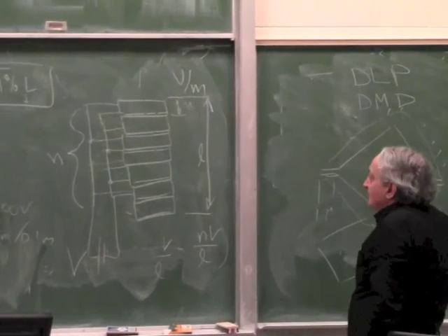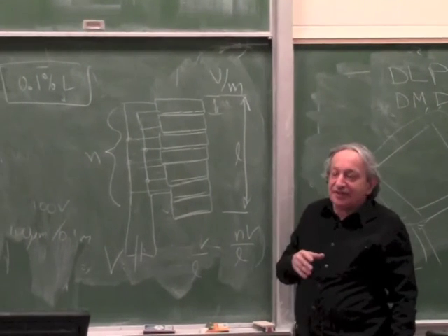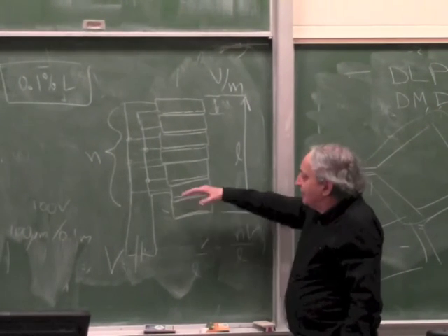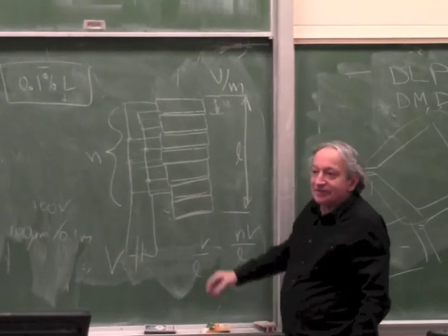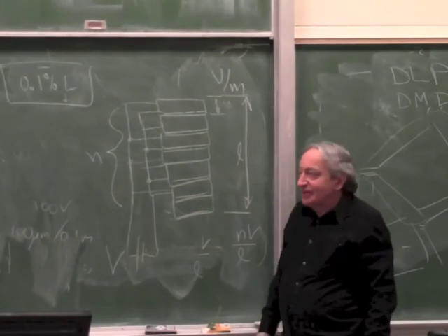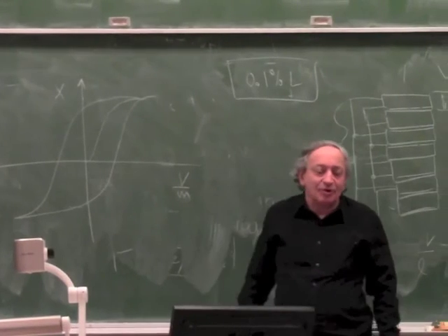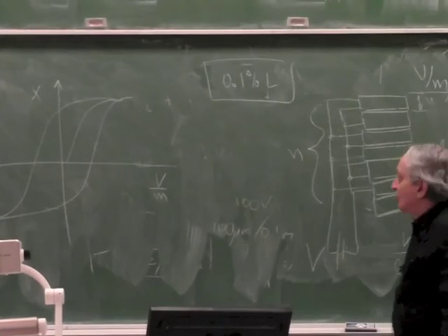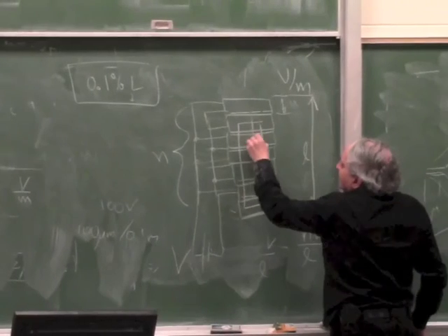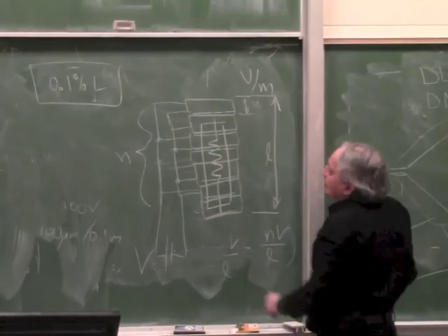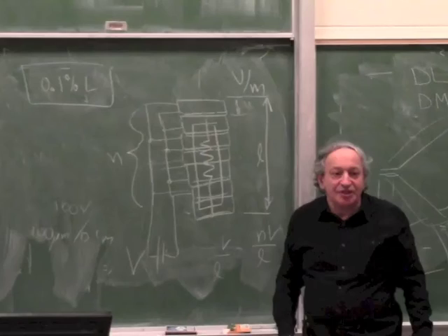Okay, so the first problem, the need for a very high electric field, is solved by cutting into layers. So you increase the electric field. Now the second problem, that it has hysteresis, is a bigger problem, and usually it's solved by sticking a strain gauge on the whole stack and closing the loop with the strain gauge.